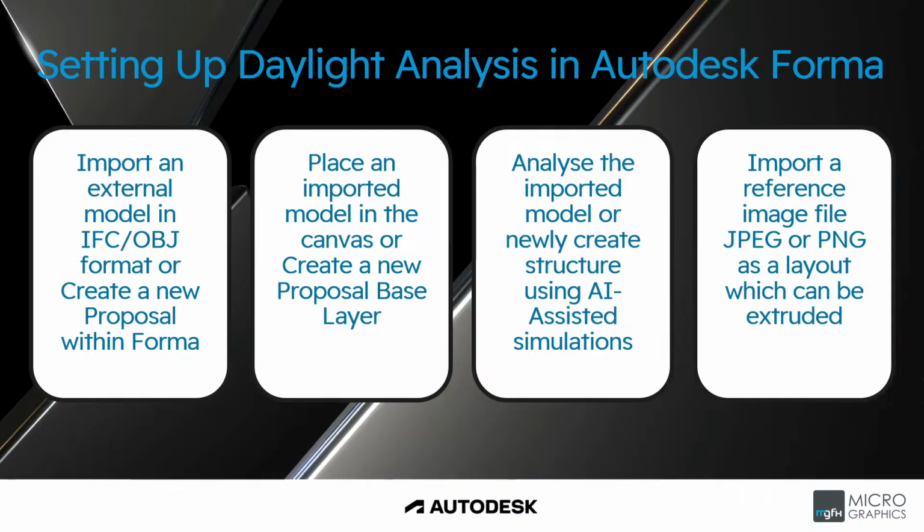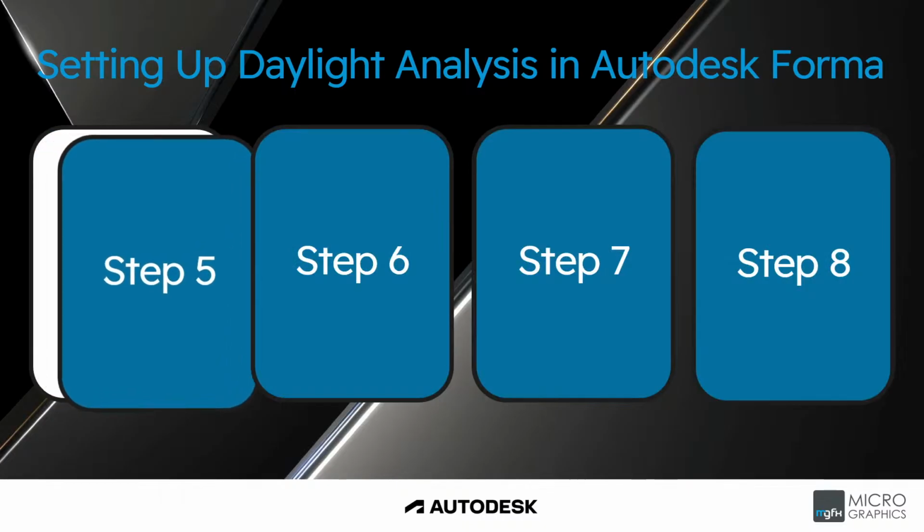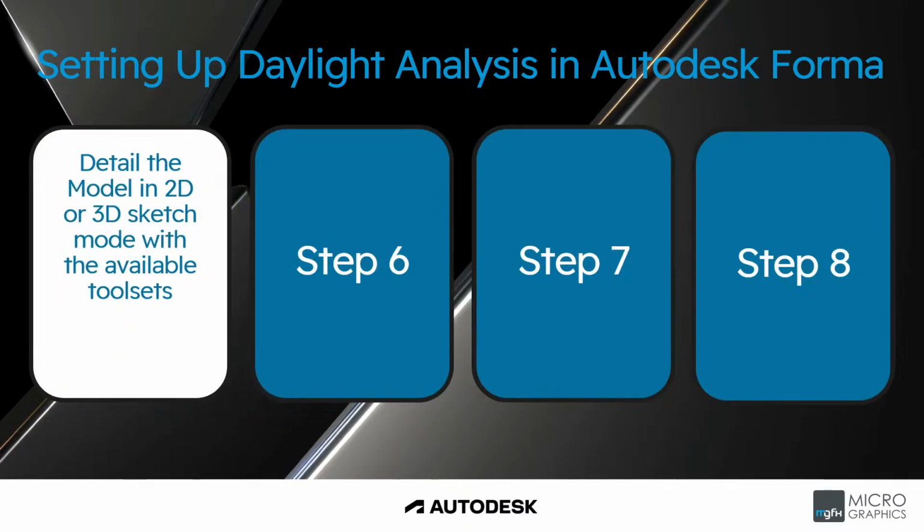You can also import a reference image file, such as a JPEG or PNG, if you already have a layout which you wish to create within Forma, which can be drawn and extruded. Step 5. You can detail the model in 3D sketch mode with the toolsets available.